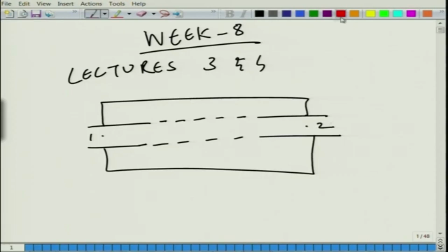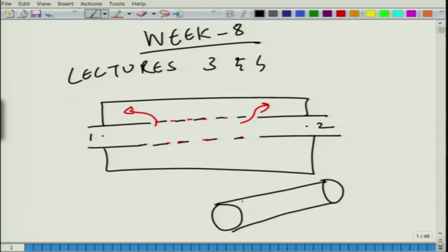And here this part is your perforated section. So what does it really look like? What I have always been insisting is that it guides the flow, does not allow the flow to freely expand, and allows the waves to interact with the annular cavity and the neck extensions. So, basically here we have a sort of a pipe. So, this is perforates. Now I am going to show you some nice photographs of